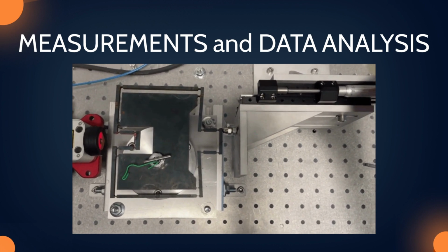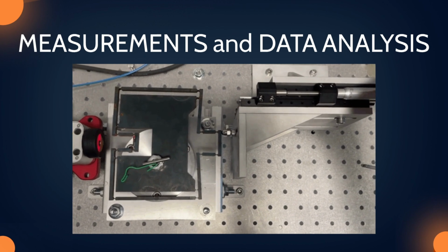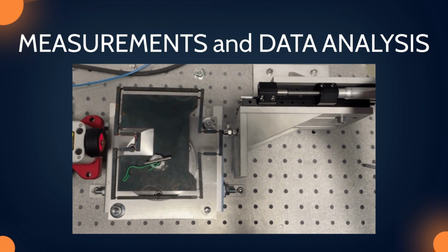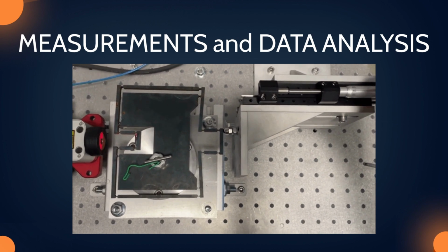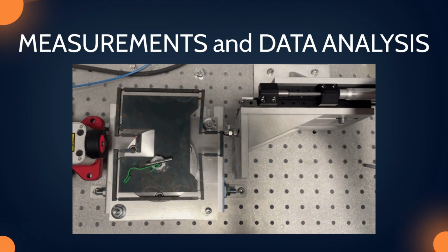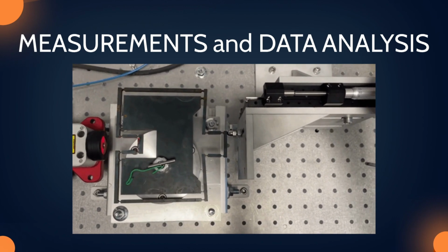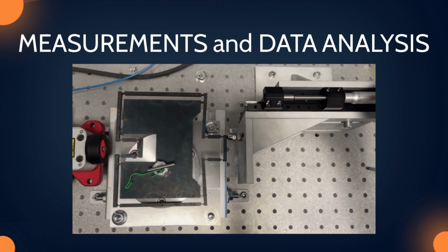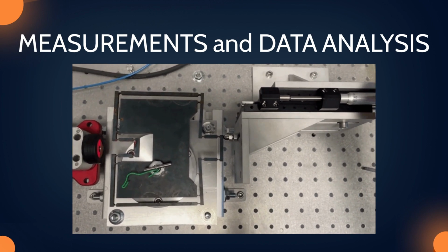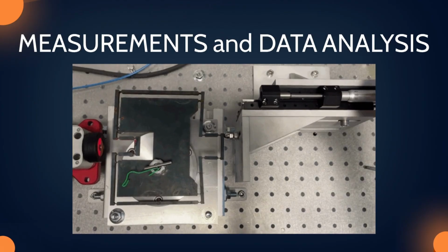During the measurements, some issues arose. First, as is visible in the video, the application point of the force was not aligned with the center point of the input. Second, due to the thickness of the hinges, the rigidity caused the system to be subjected to a higher force than the Kelvin clamp could handle, making it impossible to reach 10 mm of displacement in input.